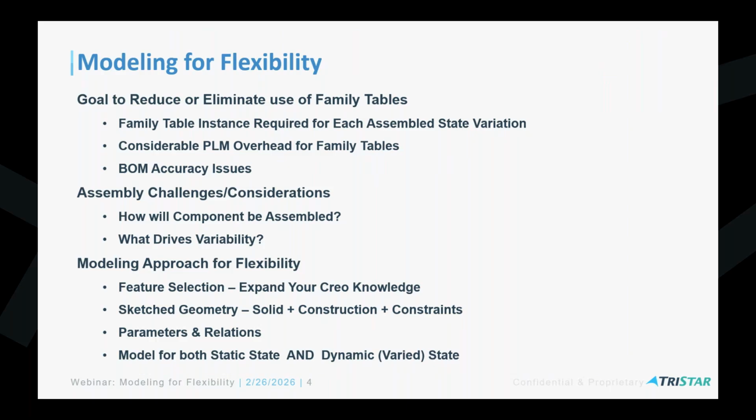Those techniques are going to deal with sketch geometry, not just solid geometry, but also using construction geometry and constraints within the sketch. We're also going to use parameters and relations to help drive the flexibility. And when we model these parts, we have to model them for both the static state and the dynamic state, or how it's going to vary.